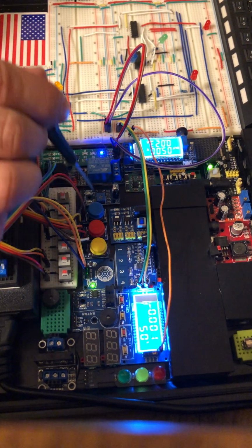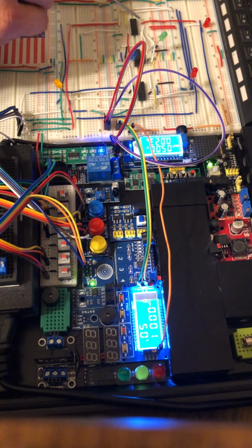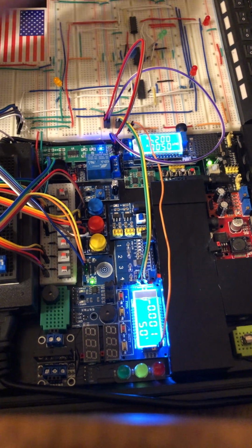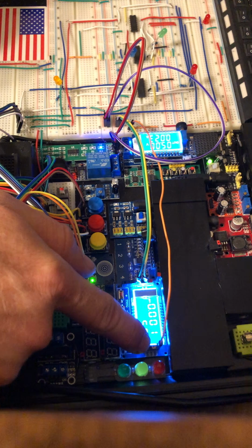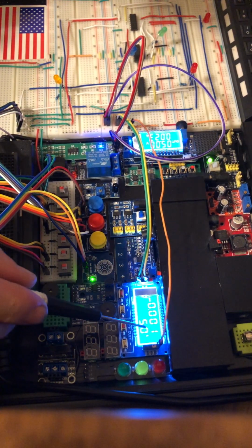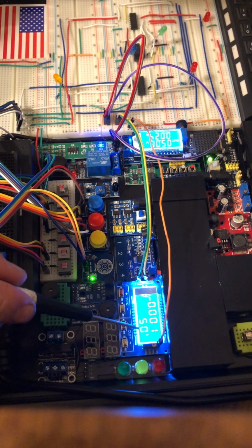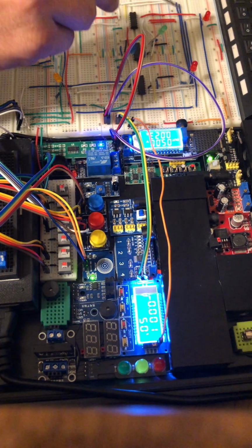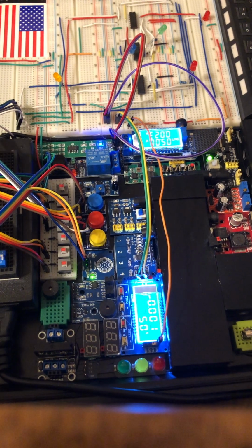Once you hit those 4 inputs, it's going to hold the signal on that last AND gate, and then it's going to flash that light with that 1, and also a 1 that we're sending from this clock pulse that we're generating. We have a 1 hertz frequency at a 50% on, 50% off rate, and you'll see that in our flashing light, half on, half off with the timing.